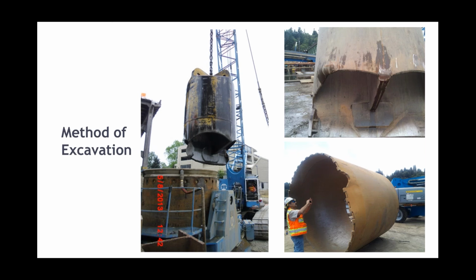How does that relate to constructability? Well, you can imagine as we drop this chisel on screaming hard rock, all the vibrations that come about. And if we have vibrations, there's more chance for this granular material to cave in against the casing, and you risk losing the casing. And this is very expensive casing that no one wants to leave behind. So that's sort of an insight into the construction risk that we were hoping to mitigate.